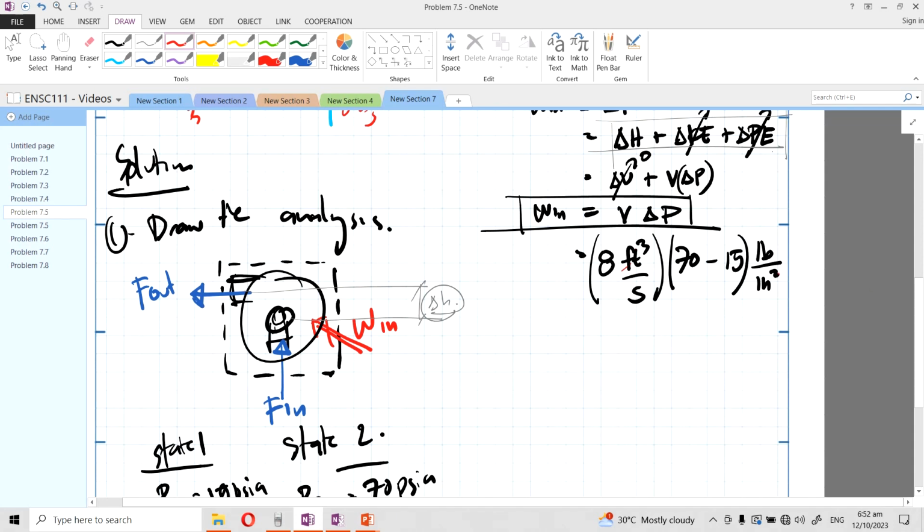Right, so to check the units, we have a unit of length here. Feet is a unit of length. Inch is also a unit of length. Then we have to convert one to the other. Now, which one? Recall that the unit of energy we know so far is the foot pound. Since we are in rate form, that means foot pound per minute, or foot pound per second. If we want foot pound per second, then we need to convert inch to feet.